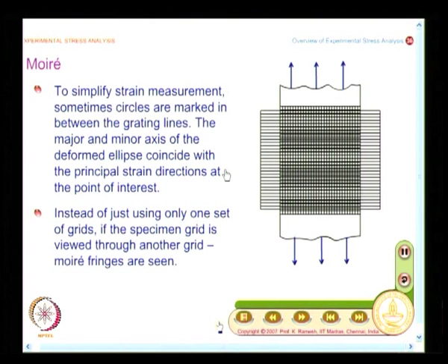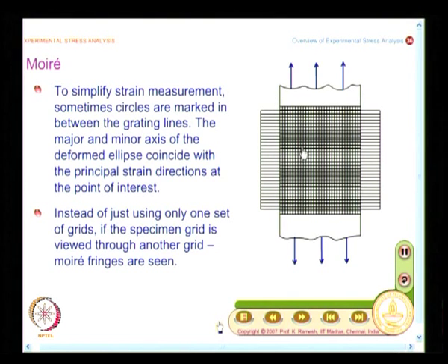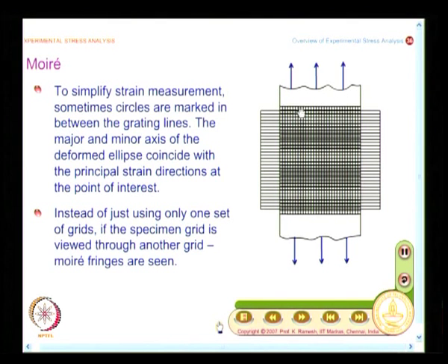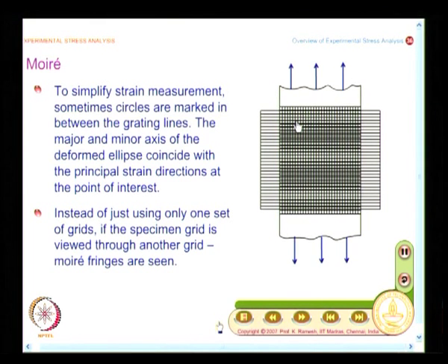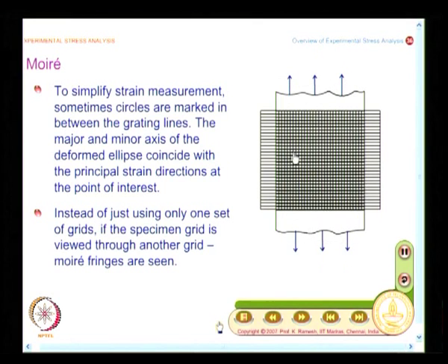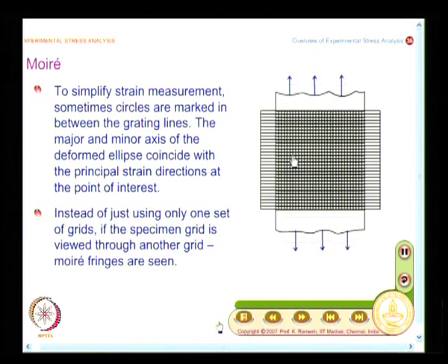So, if you look at this diagram very carefully, compared to that, this is a simulation where I have some control over the way I move the specimen grating, and here the specimen grating is a checked pattern. I have a reason for it, because in some applications I get only one piece of information, in some applications I will do one experiment and try to get two pieces of information, we will see that. And what you find here is, this moves slightly, but I see a number of fringes. So, indirectly you can understand that it is some sort of magnification effect that Moiré helps you to measure.